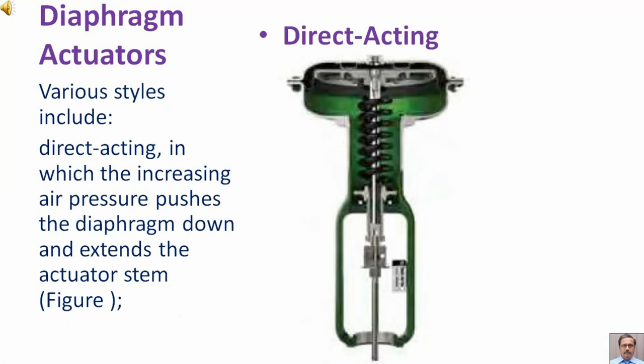Various styles include direct acting, in which the increasing air pressure pushes the diaphragm down and extends the actuator stem, as shown in figure.